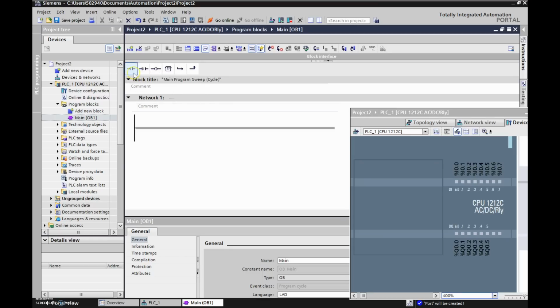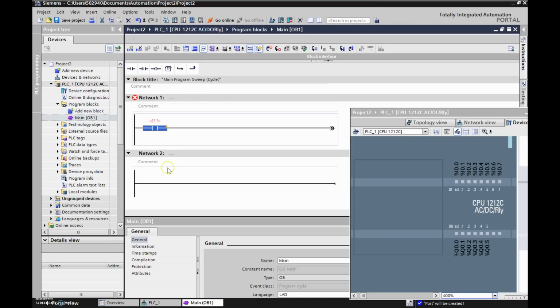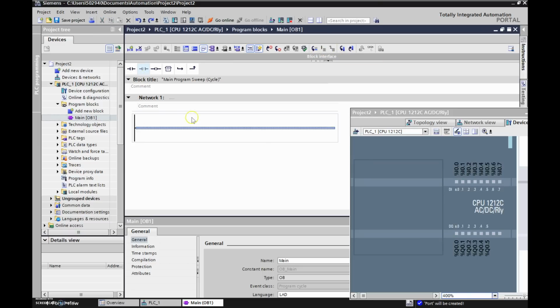So let's grab it. Just hovering over it, seeing whether... here, let's hit undo. Where do you find undo? Okay, there we go. So they call this a normally open contact. I'm going to call this an examine-if-closed contact, just the same as the Allen Bradley. But in the Tweedo Suite and in the Siemens, they will be calling it a normally open contact. I'm going to call it an examine-if-closed.